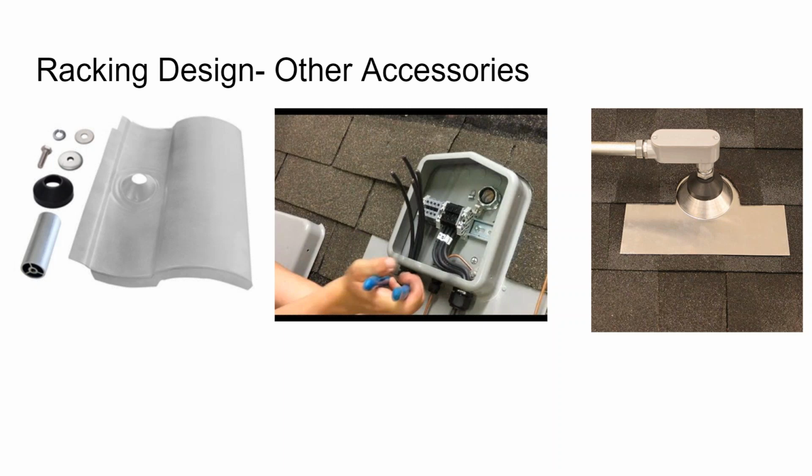Let's see. The average sunlight across the country is 1 to 1.5 kilowatt hours per year. If there's a single string of solar modules that is broken, the problem is probably in the connector between the array and the components. Component failure is rare. Workmanship and installer error is common. So it's going to be in the field-made component. It's going to be in the MC4 home run connector.